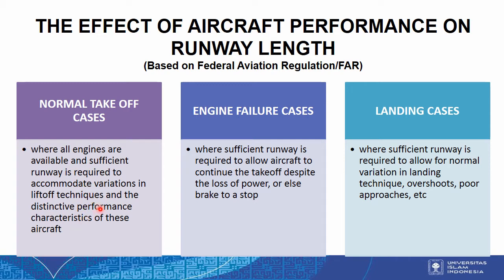And the second is the engine failure case, where sufficient runway is required to allow the aircraft to continue the takeoff despite the loss of power, or else brake to stop. So this is when the aircraft has engine failure.